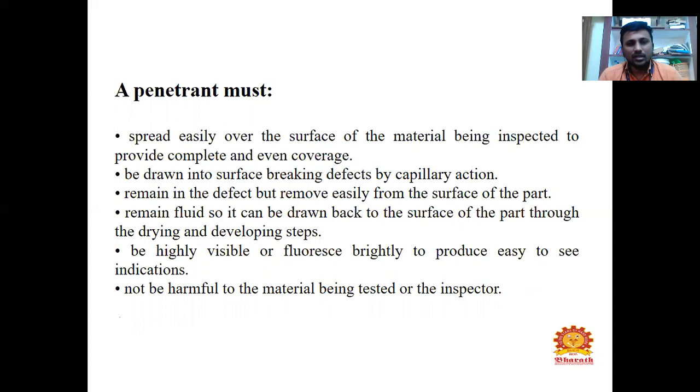It must be drawn into surface-breaking defects by capillary action. And the third major point: while remaining in the defects, it must be removed easily from the surface of the part. So apart from the defect, we need it to be easy to remove. Okay, that's the major importance of the penetrant.